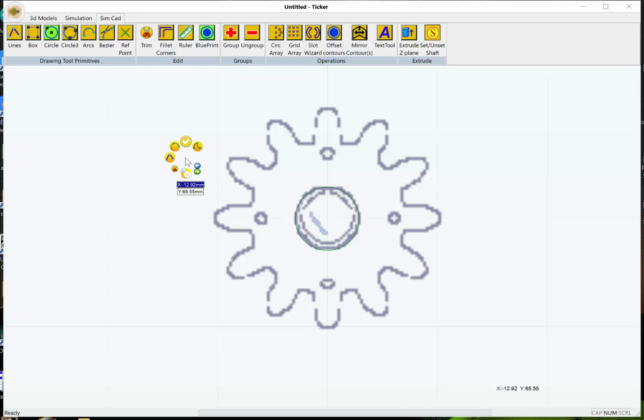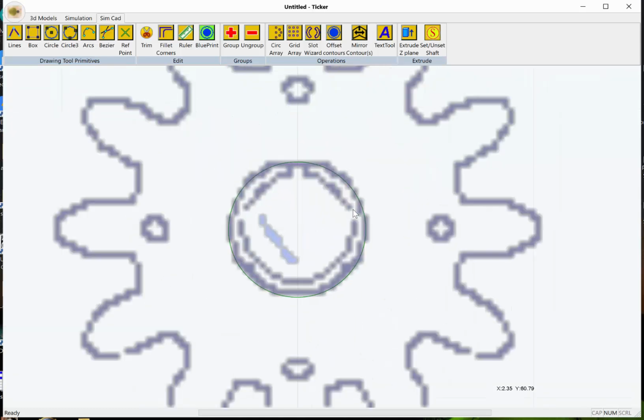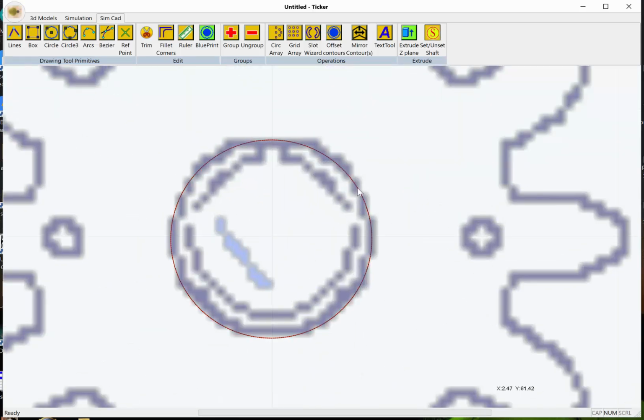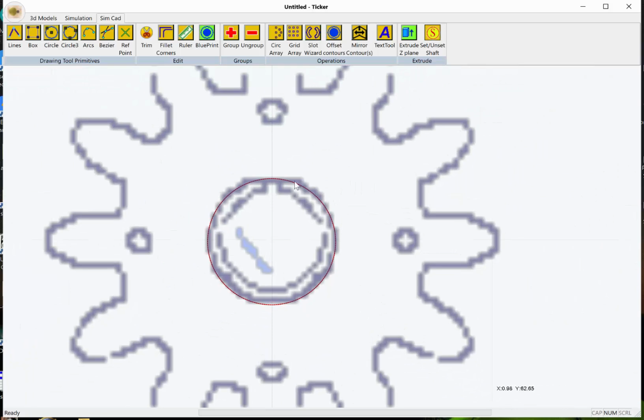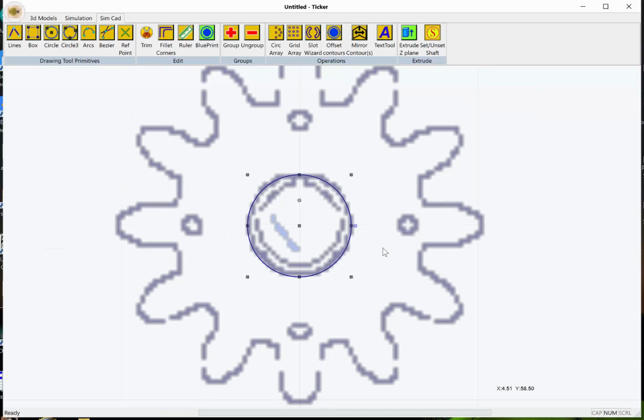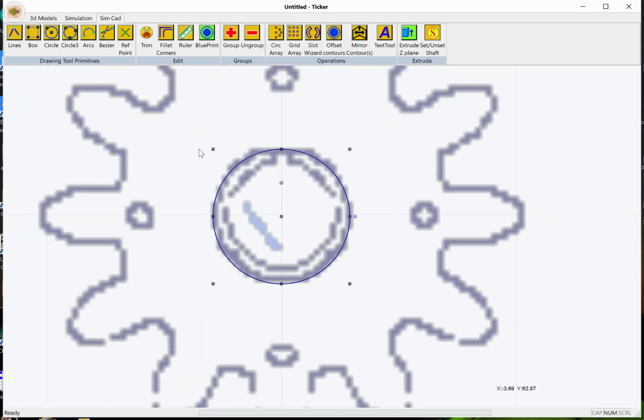I'm going to right-click on my context menu and hit the check mark. When you hit the check mark, if the tool doesn't exist in this menu that you're currently using, the tool will turn off, and you can see circle just turned off. And that means we can go in here and select our circle that I just drew, and it turns red because it's selected. In this CAD program, if you select something which is already selected, it will go into what I call blue motion mode. Everything turns blue, and you get handles with which you can stretch, move, and adjust things. You can grab your object with the center handle and center it to a much better proportion.